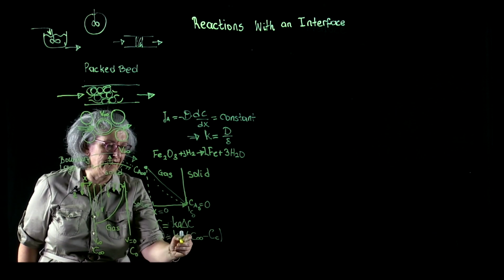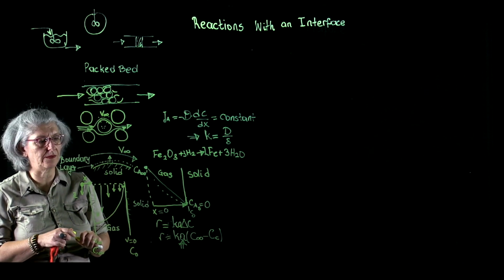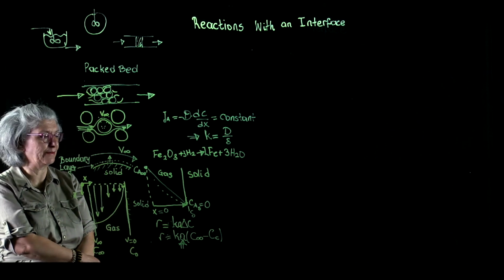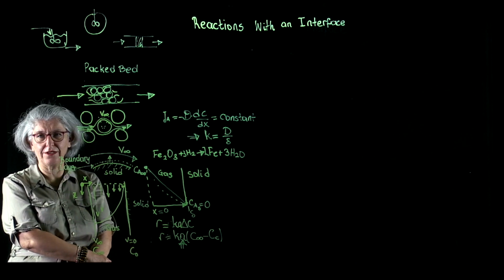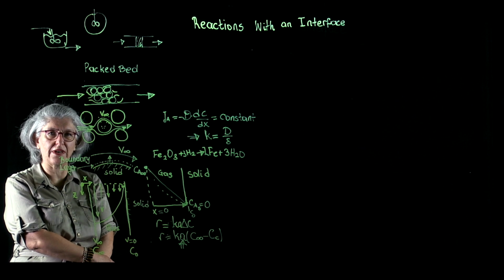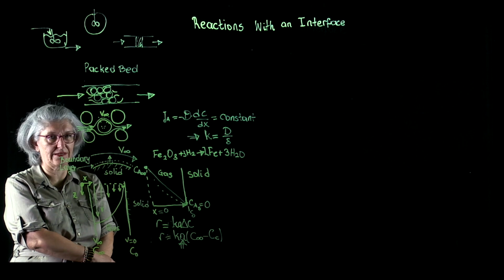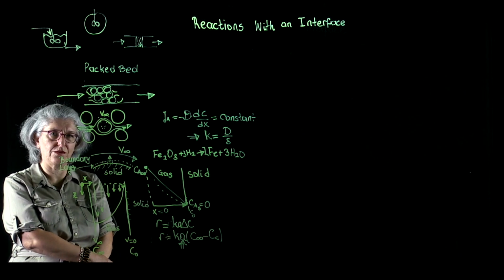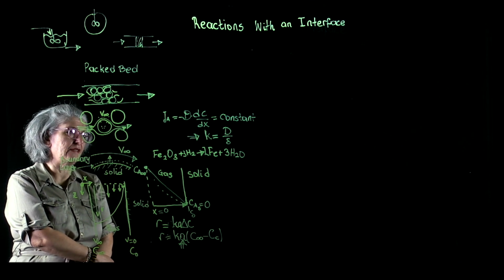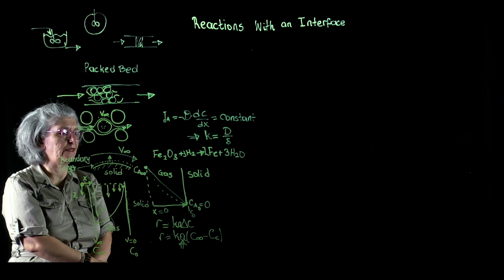This interfacial area is the biggest problem of all the chemical engineering problems, that we have no way of measuring that A directly, and that A, depending upon the types of the reactors, may not be constant. But let's leave that discussion to our fluid-fluid contact reactors. So here now we have our mass transfer coefficient at our disposal.